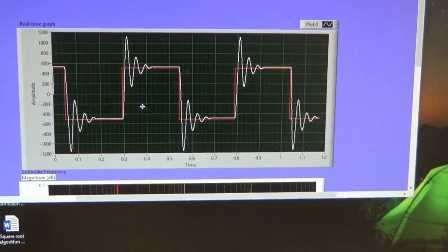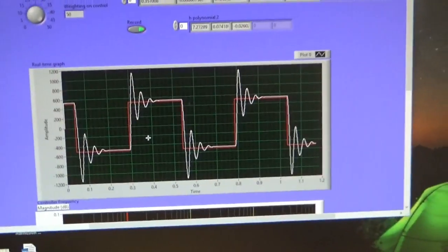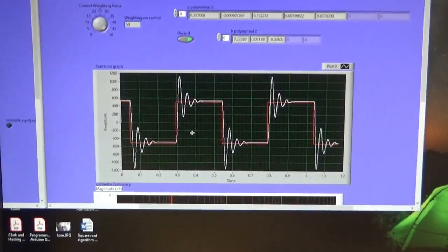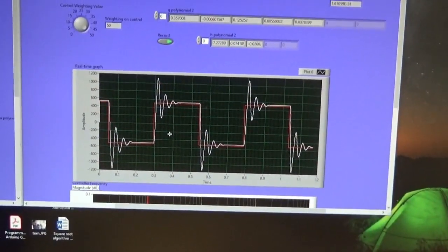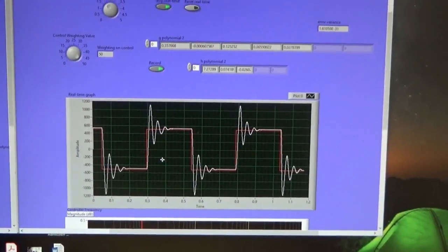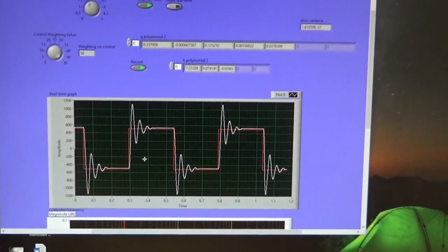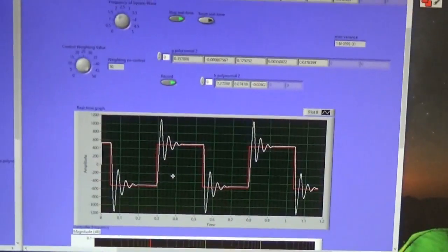So we've got much more overshoot because our mathematical model isn't right. It hasn't taken effect of the integrator within the motor itself. We've just kind of ignored it and modelled just from velocity instead. Whereas we need to measure from position.